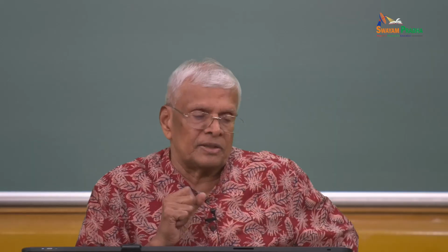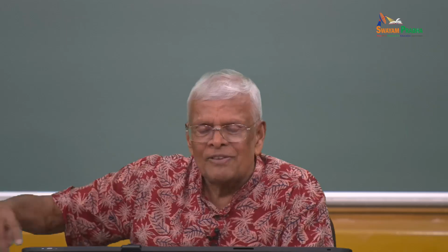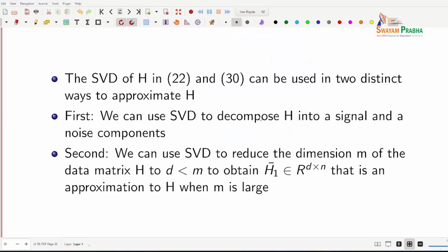So, the larger lambda represents signal, smaller lambda represents the noise. By separating the larger ones from the smaller ones, to help separation I am going to help you with the beta. So, by choosing beta to be 0.1, 0.05, 0.01, how do you decide this beta? That is a $1 million question. That is often decided by the plot of lambda. If it becomes flat in the tail end, the flat region of lambda in the tail end generally represents noise. Why? The noise has a variance which does not change. The noise variance is constant.